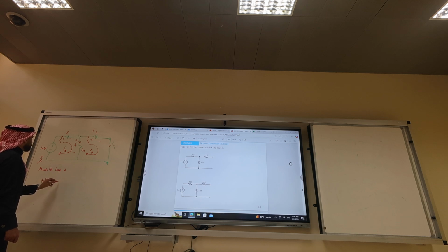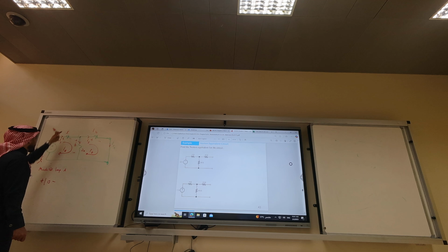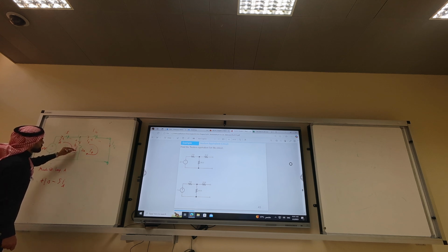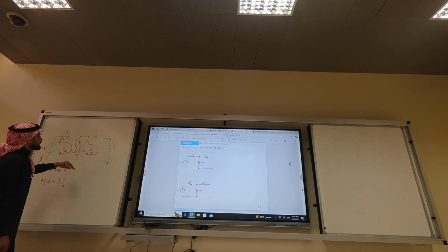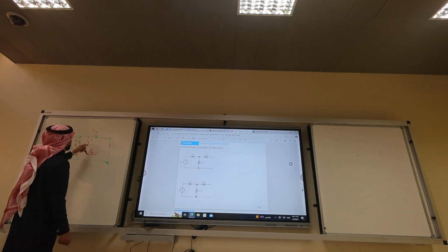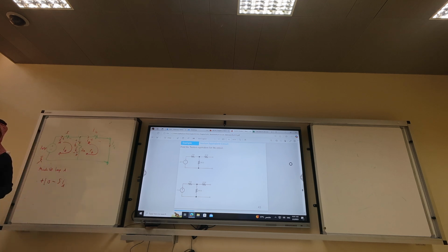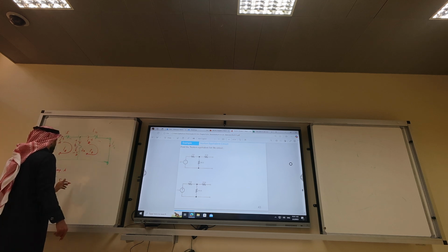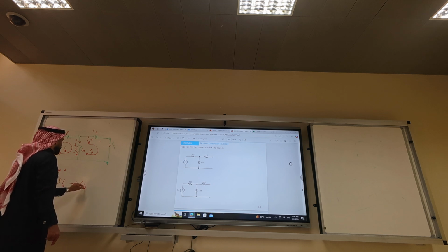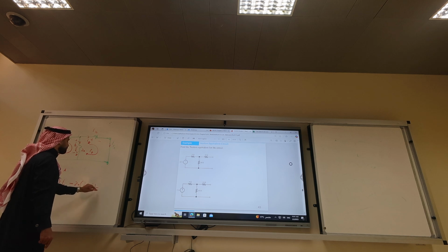Minus, because it's a voltage drop, 5 times IA. That's I1 is IA. I2 is IA minus IB. What is I3? IB. Get it? So we do KVL: 15 minus 5 IA. Rise or drop? Drop. 20 times IA minus IB equals 0.